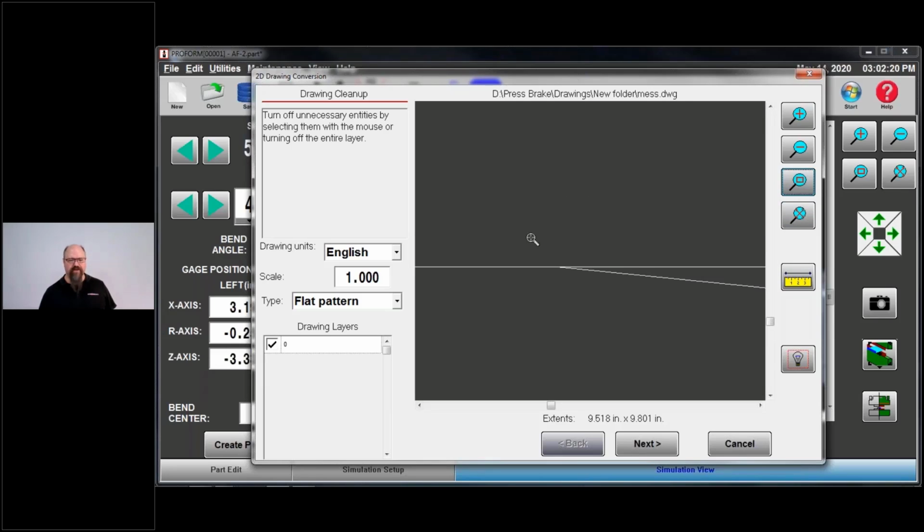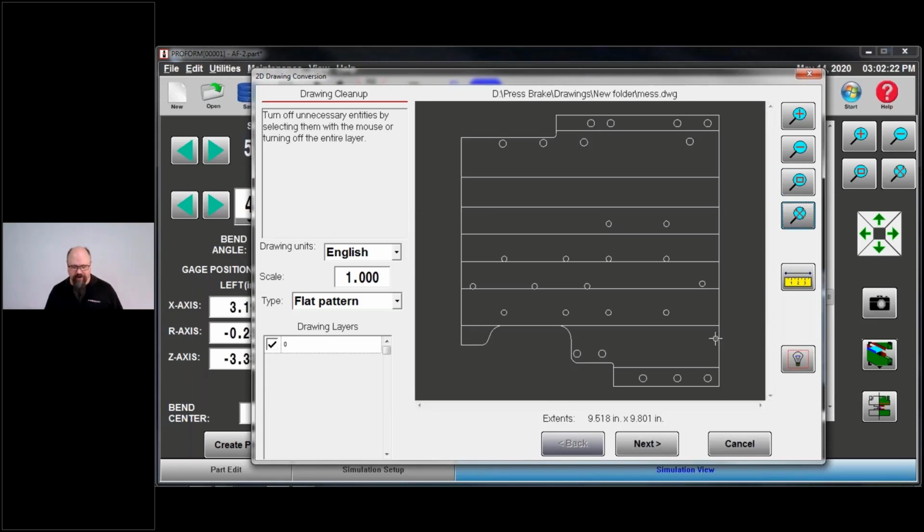No, it was one of these that intersected, and I might not be picking the right one. But in several cases, the actual bend lines intersected with a cut line. You cannot have lines that intersect each other. The lines have to land on the radius or at the actual side, okay? So I had to send this back and say, hey, you need to go over these again and clean all this up because those have to land. They cannot intersect.